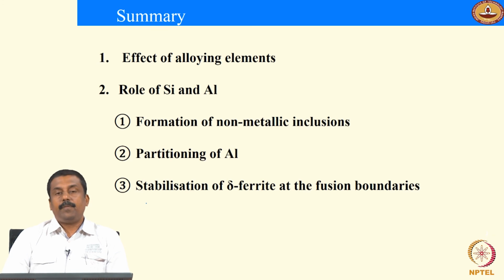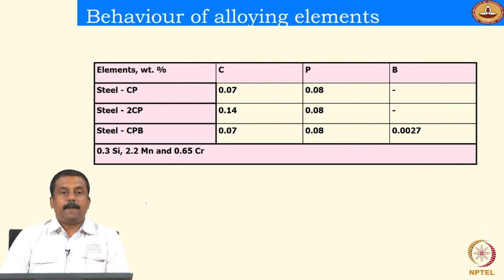So from a steelmaking point of view, to generate microstructure, phosphorus can be used to a certain extent, but phosphorus is extremely bad when you consider welding, because phosphorus segregates to the grain boundaries and interdendritic boundaries during solidification, and we will see how the segregation happens and how we can avoid the detrimental segregation of phosphorus in this class.